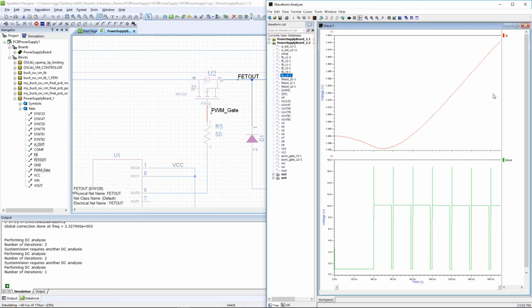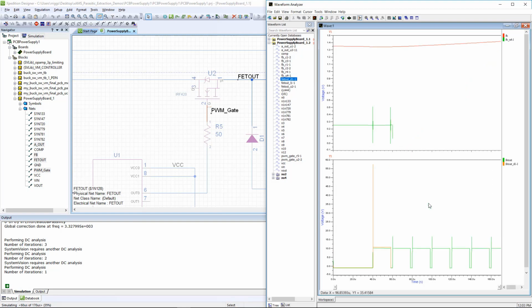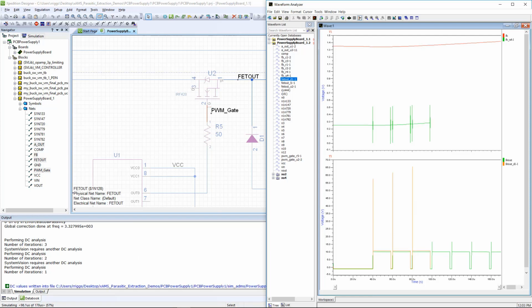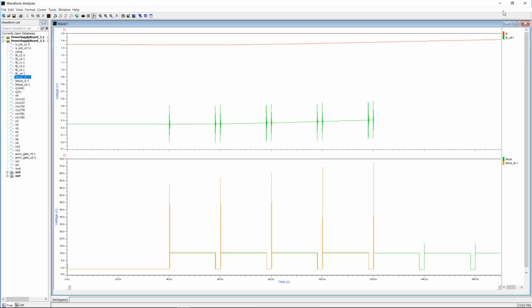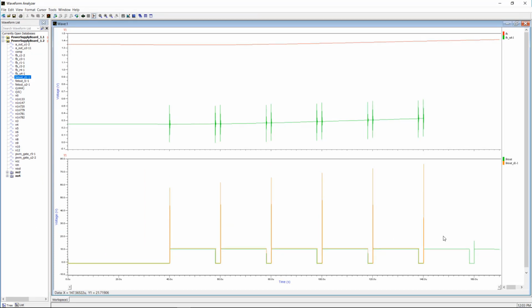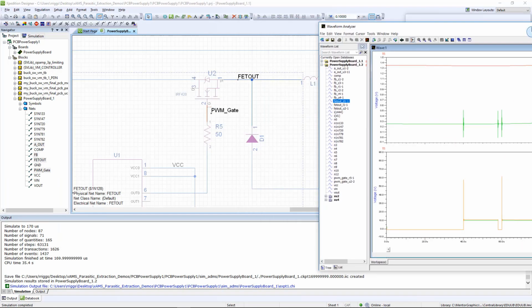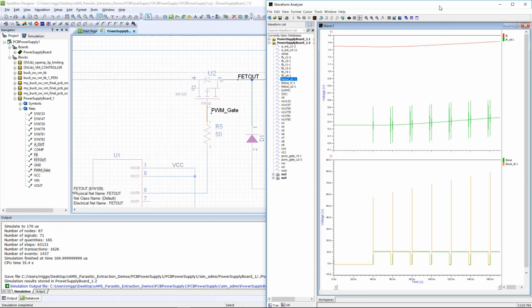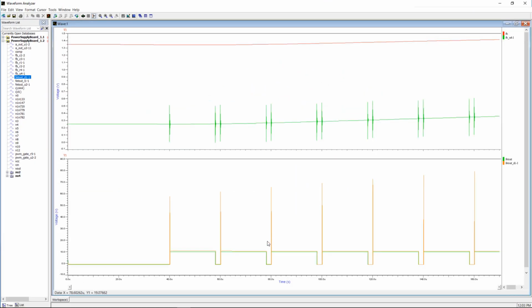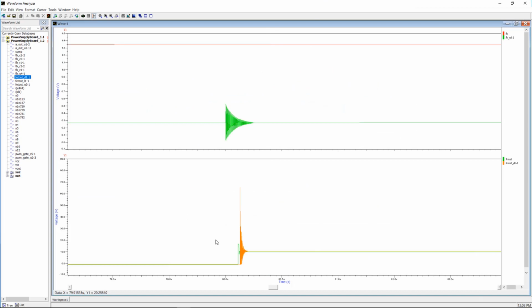In the past, we may assume certain ideal circuits or ideal rules of thumb are okay to ignore, but with this parasitic extraction, we'll find that there are certain resistances or inductances or capacitances that we can't simply ignore. We don't live in an ideal world, and they actually do add noise into our system. So zooming in here in the graph, you can see in green the ideal waveform, which assumed no problems, but in reality when we add the extracted parasitics we see some ringing and some oscillations.